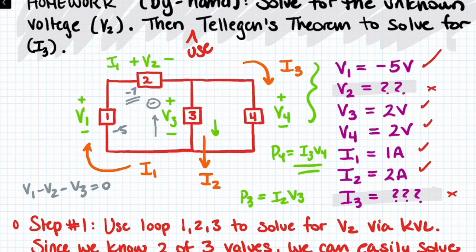I1 and V2 satisfy the passive sign convention. So P2 will be equal to I1 V2. Now the only outlier here is V1, which does not satisfy the passive sign convention. We could flip the voltage and account for that, but really we could just take a shortcut here and say that P1 will be equal to negative I1 V1.